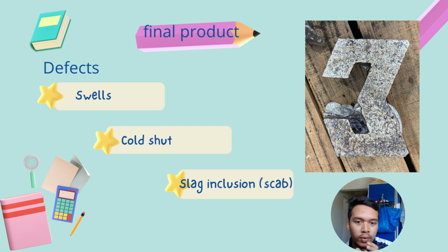The ways to remove slag: first, melting the metal with a flux in a vacuum or in an inert atmosphere. Second, adding ingredients to the mixture to cause slag to float to the top where we can easily see and remove it before pouring, or use a special ladle that pours metal from the bottom. And lastly, adding a ceramic filter into the gating system.